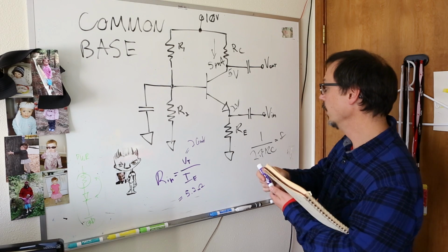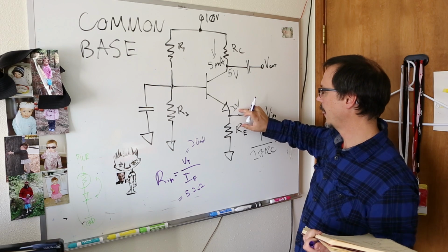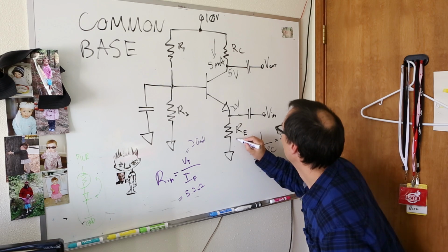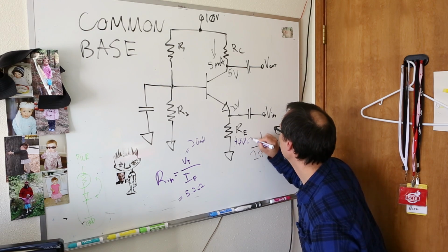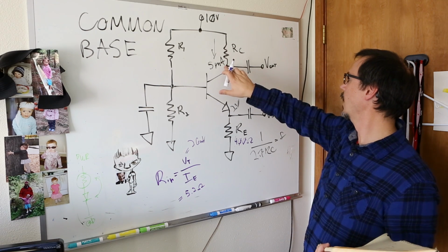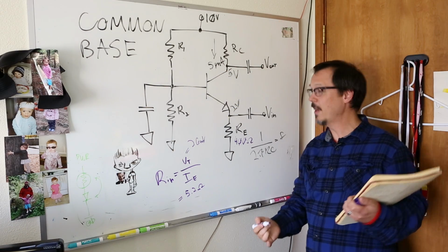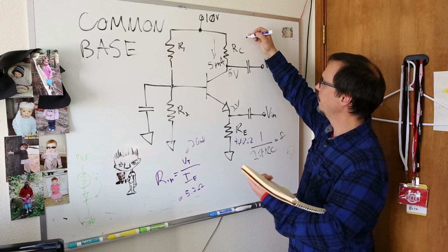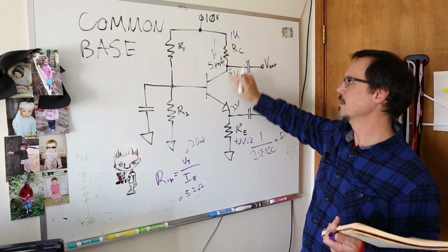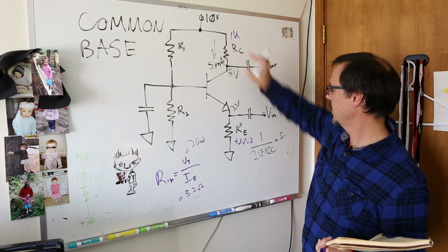That's nuts. More importantly, with my choice of 2 volts, I know that 2 volts divided by 5 milliamps is going to be 400 ohms for the value of RE, our emitter. Now I also know that since I've chosen my quiescent point to be at 5 volts, so I get maximum upswing and maximum downswing at 5 milliamps, I have a value of 1K for my RC, which is the resistor collector. So I've got values for this, I've got values for this.